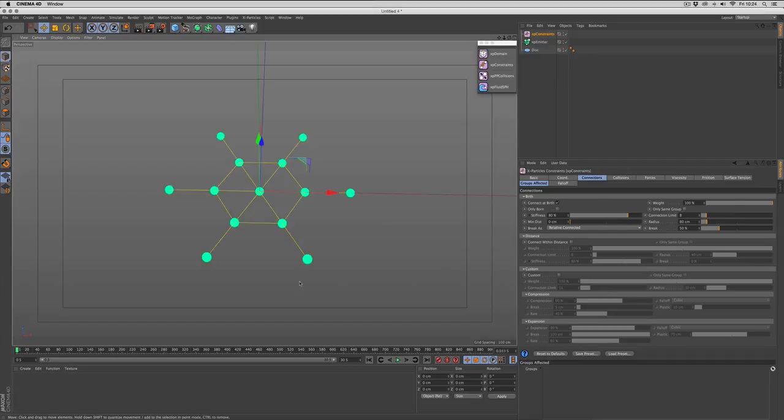Go up one frame, and here you can see displayed the actual constraints. What that's doing is creating this spring between each particle, and that's going to keep the particles together with various options on stiffness, the radius, and the breaking. We can add more in by enabling either higher constraints, radius, or connection limits. Let's put this to 12, this to 200. Go back and up one frame.